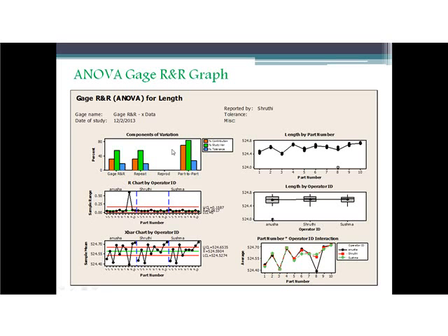For a good measuring system, the largest component of variation is the part-to-part variation. If instead large variation is attributed to the measuring system, the measurement system may need correcting. In our case, part-to-part variation has the largest variation component, so our measurement system needs no correction, it is good. Coming to the R chart, it is the control chart of the ranges.